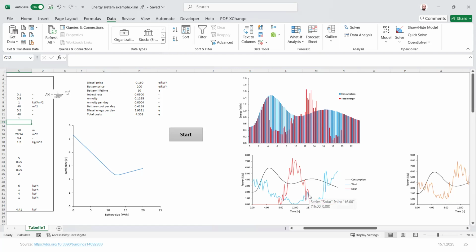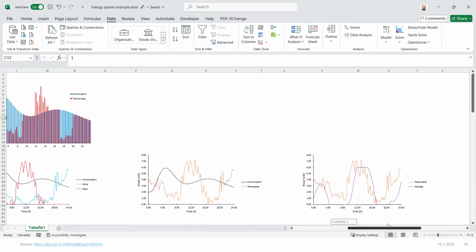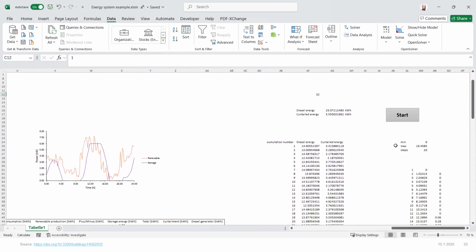I have a normal distribution and I subtract random numbers from it. What that tries to mimic is cloudiness or changes in wind speed. So there's a probability density function for the wind speed and also some kind of a probability that there are going to be clouds. So what that means for my outcome is I can make a Monte Carlo simulation.